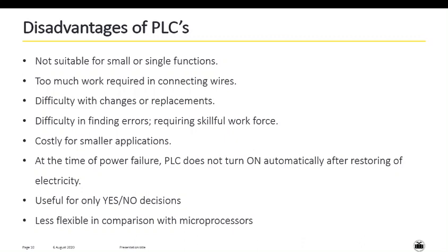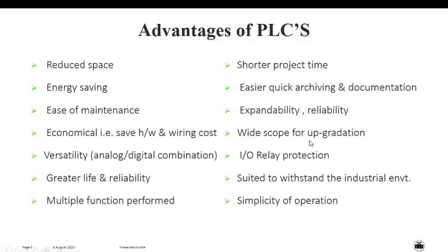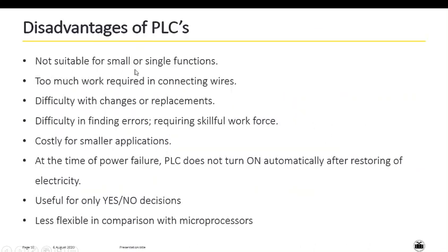I have told you this has scope for upgradation, but while purchasing the PLC, if I have purchased a PLC of fixed configuration, then we cannot change or replace the input output or upgrade the PLC. So there is a difficulty in changing these input outputs, and in this case you have to replace the PLC.